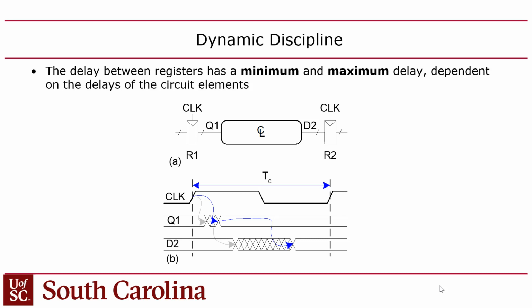Before the setup time. Makes sense. This is why it's risky to overclock a chip, overclock a CPU, right?